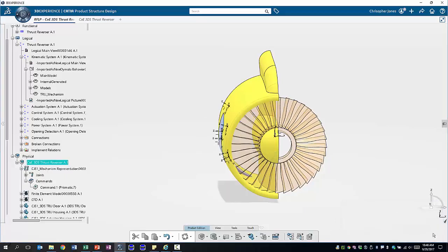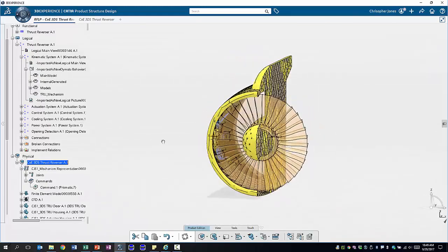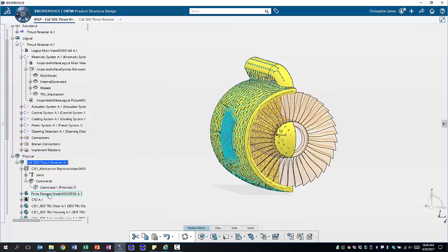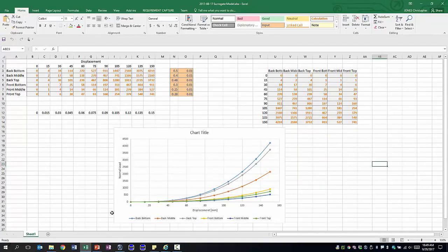Now that the physical model has been built and defined, we could define the mesh of our system in order to then run a detailed CFD analysis using our simulator tools. Having used the CFD tool to calculate the loads on the 6 points of our door, depending on the opening of our door, we can generate a surrogate model. A surrogate model in this case is nothing but a table-based model which, depending on the displacement or opening of the door, applies a different load onto the 6 different points.